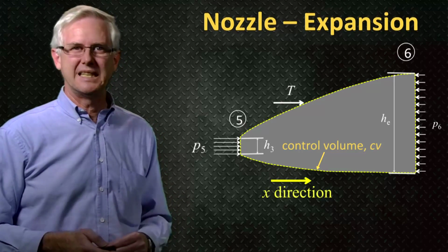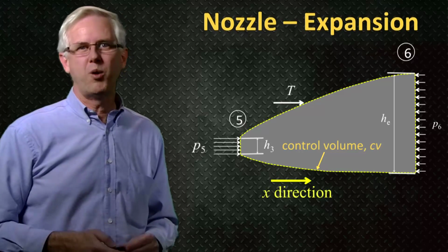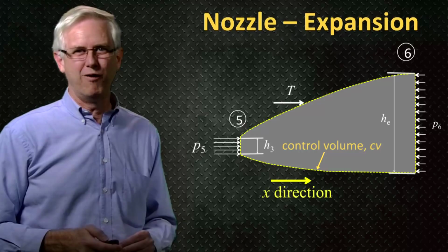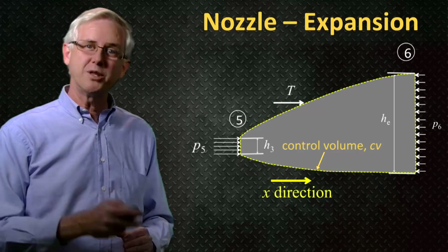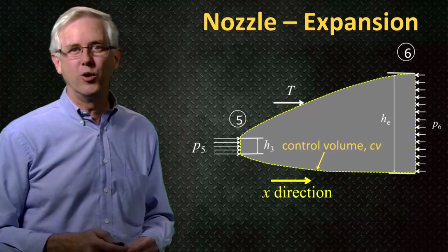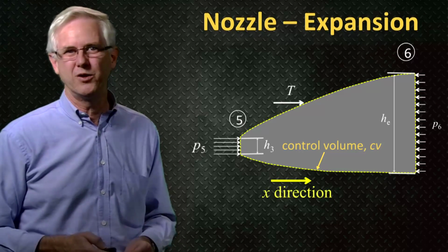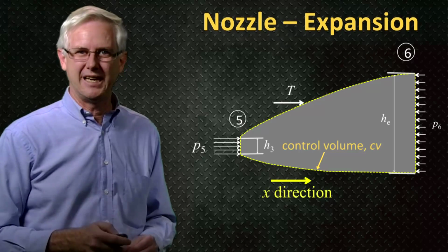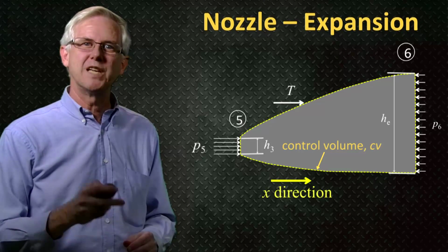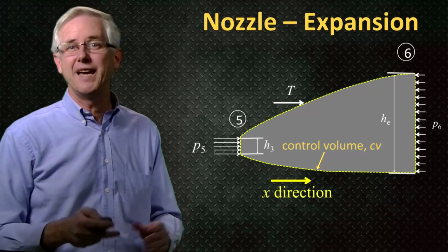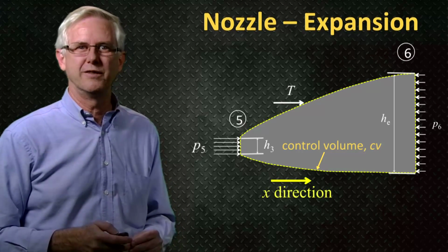Let's call that T. Another important point here. T is the force acting on the control volume. An equal and opposite force acts on the scramjet nozzle, and that force is the thrust force on the nozzle. You'll have to do some careful thinking and modelling here and balance the forces acting on the control volume with the change in momentum flux of the air passing through the control surfaces.